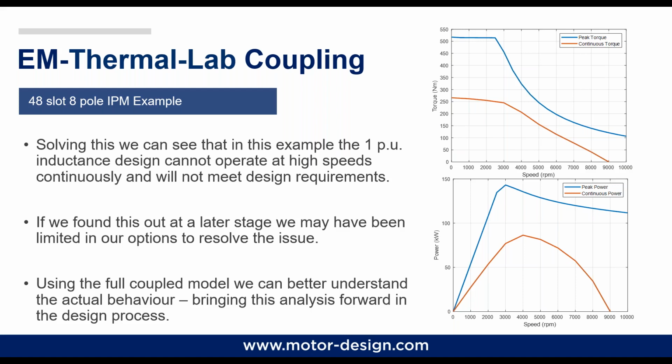The reason behind it is that the current basically is not the only effect to consider, since it is not the only heat source inside the machine. So there are loads of other loss components inside the machine, like for example the aero losses, the AC winding losses, or the eddy current losses inside the magnets, and loads of other small things that basically end up with this machine that is not able to operate continuously at 9,000 RPM.